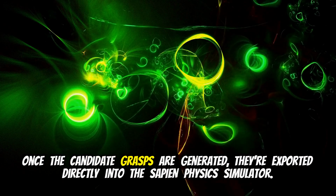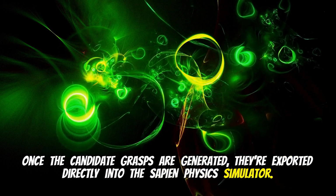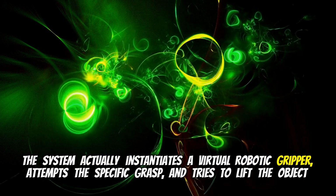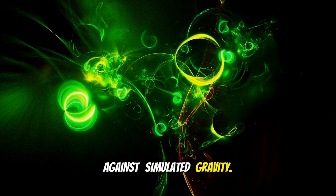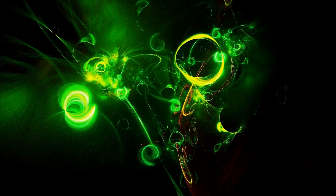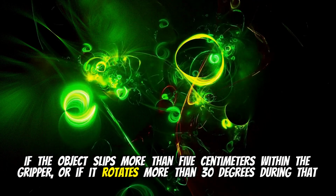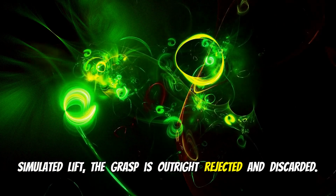Once the candidate grasps are generated, they're exported directly into the Sapien physics simulator. Okay. The system actually instantiates a virtual robotic gripper, attempts the specific grasp, and tries to lift the object against simulated gravity. And they set incredibly strict physical tolerances for success here. If the object slips more than 5 centimeters within the gripper, or if it rotates more than 30 degrees during that simulated lift, the grasp is outright rejected and discarded.